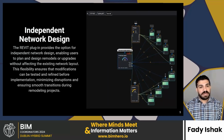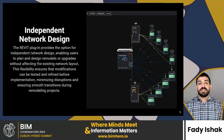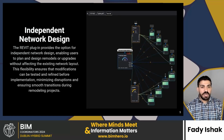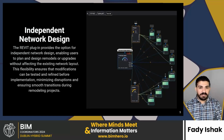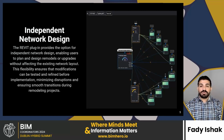Another feature we've created in this plugin is that it can come as an independent module. We can create a module just for the network topology where the PoE or the data network designer can go about designing his network and creating all the connections without relying on the 3D model. This network design is eventually imported into our Revit plugin that has both modules, and from there the modeler can start planning the cable routes and different 3D modeling characteristics in order to house that system.